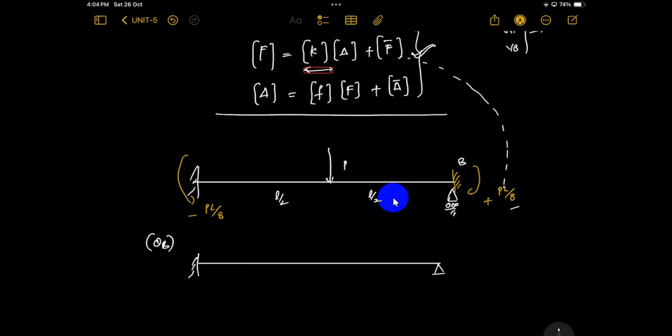See, I will write it. You will give unit displacement. See, unit displacement theta b is 1 in the direction of the clockwise. Give it. You will get this unit. How much force arises? 4EI by L. You know it, because if you apply moment, see, I will write here.